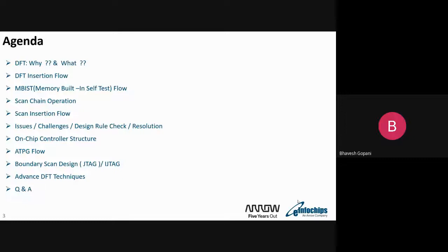After the post DFT, post silicon, we can say. So today's agenda, we will cover the following topics: why DFT, what DFT, what are the DFT insertion flows in place, how the MBIST insertion happens, then what the scan chain operations are, scan insertion flow, certain issues, challenges, and also DRCs, and how we can fix those kinds of issues during DFT insertion.